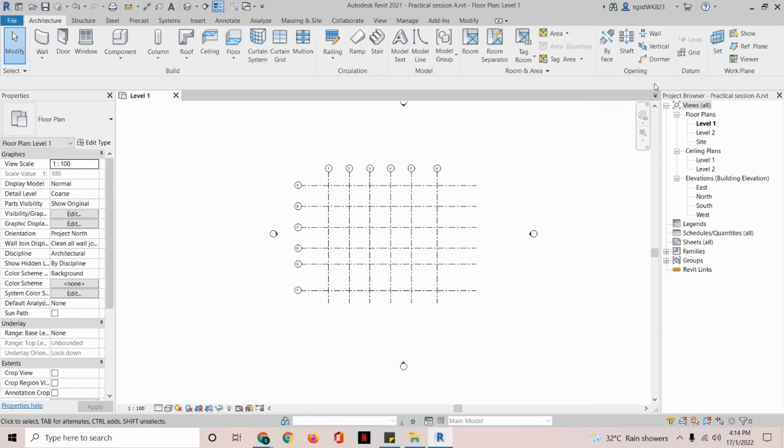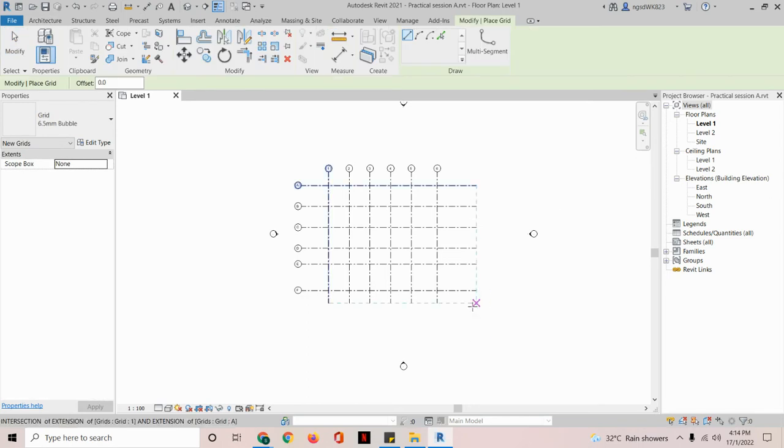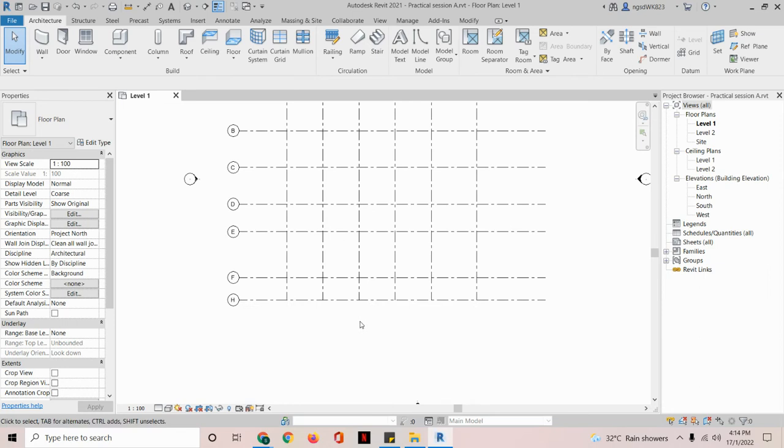So let me repeat that again. You click the grid. Let's say, for example, you create something that you do not want. This is not limited to grid lines. Any component, architectural, maybe you build a wall that you don't want or a window, you can just exit the creation mode. You will know that you exit the creation mode when there's no more green bar on this top ribbon tab.